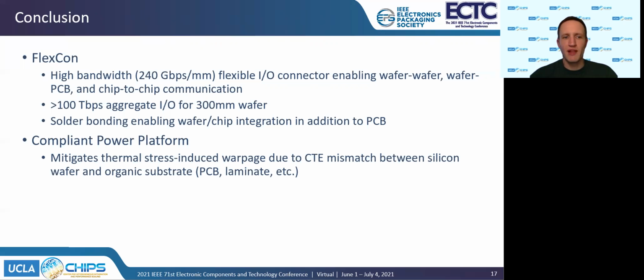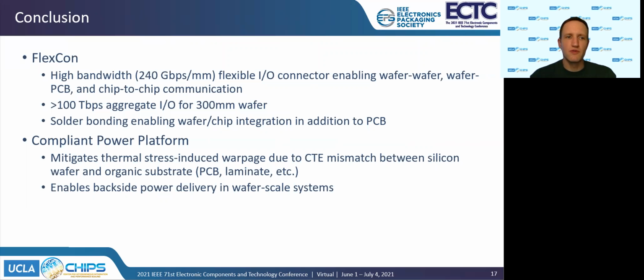The compliant power platform mitigates thermal stress-induced warpage caused by CTE mismatch between silicon and organic substrates such as PCBs and laminates. This enables backside power delivery in wafer-scale systems, but this approach can be easily extended to, for example, large-size dies on a laminate.